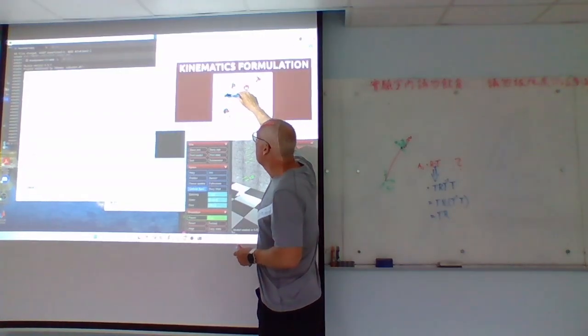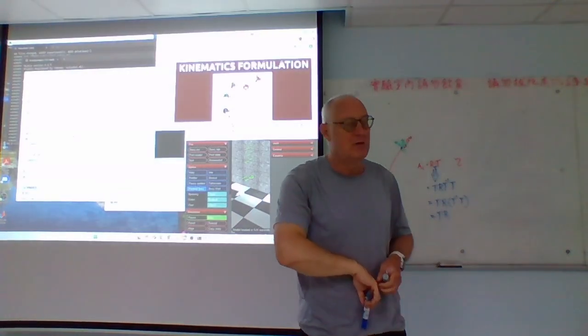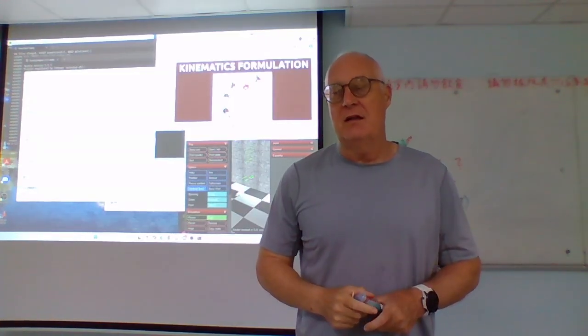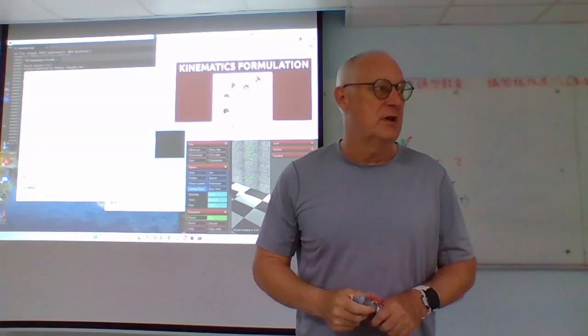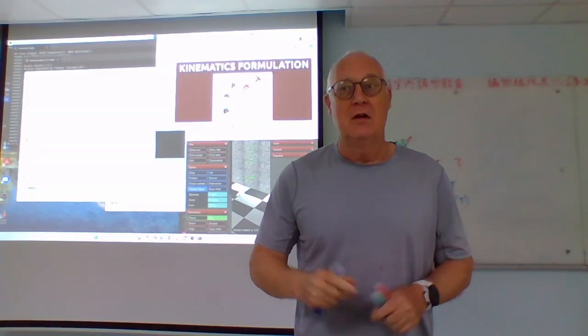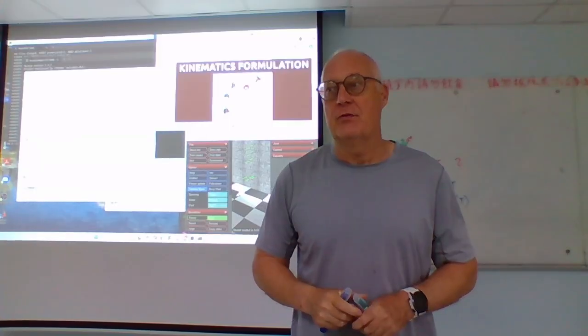I usually just assign the coordinate frames to where I want them to be, calculate the difference between the two frames, and then do the rotation. And that's a transformation matrix for joint 1, and then joint 2, joint 3, joint 4, and so forth.